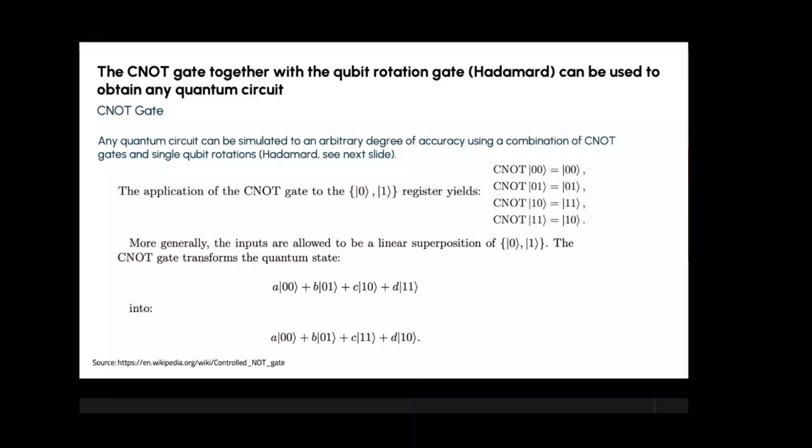So if you look at the first column here, it's the same as the first column here, but the second column is different because this is just applying the exclusive OR. So now the second column is obtained by looking: I have a 0 or a 1. Yes, that's true, so this becomes 1. Here I have a 1 or a 0, so this becomes 1. But the exclusive OR doesn't allow two 1s to become a 1, so this becomes a 0.